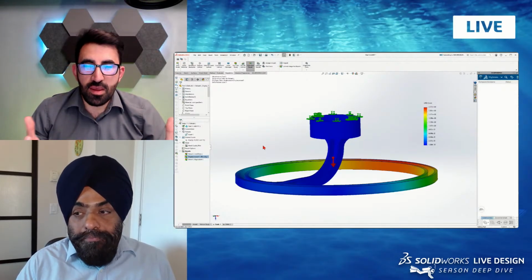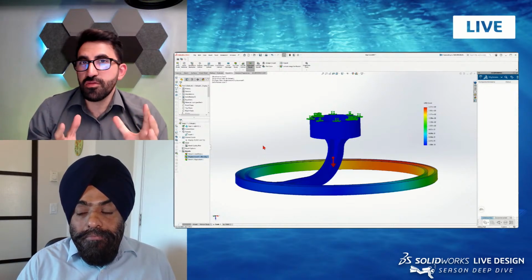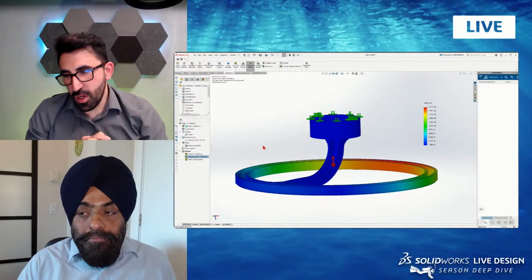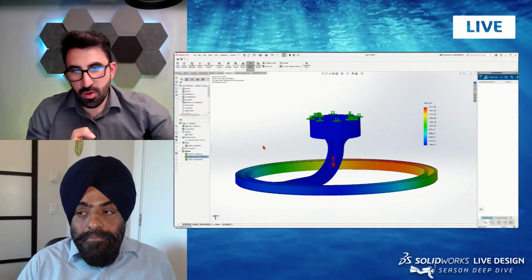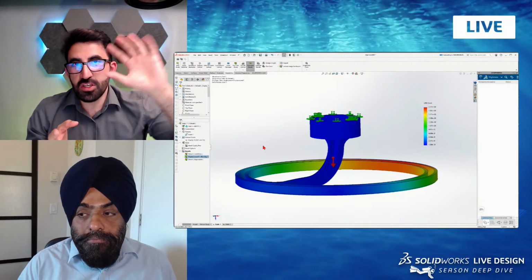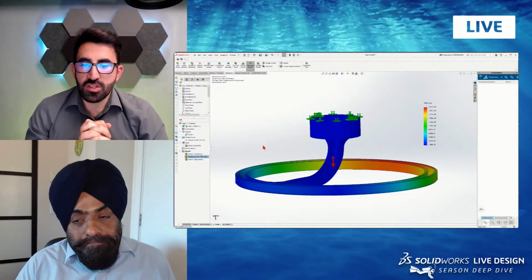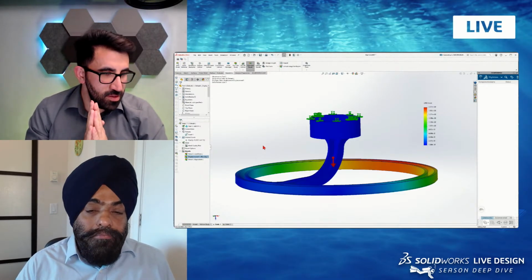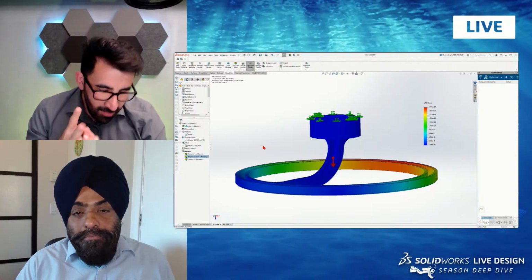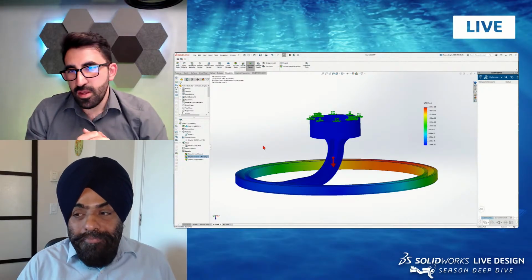designing a component. Right now, we just simplified it for the sake of the argument for making an example in just 1 hour. But if this component is going to be produced, get certified, manufactured on the shelf outside, you need to cover a lot more areas, such as risk management, material cost, manufacturing cost, deliverability of the components, and so on and so on and so on.